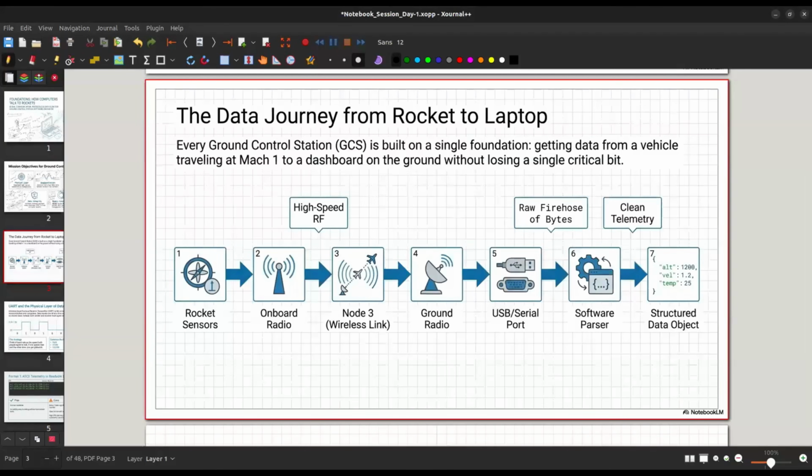Most AI application space seems to focus on analyzing data sent back to Earth. What are the biggest challenges in deploying models directly on board satellites? The biggest challenge is you cannot directly apply the AI algorithm on board unless you have a specific high-end computer for that. The mini computers that I would recommend are probably something you have heard of, Jetson Nano, and maybe Raspberry Pi 5. These are the onboard computers that you have to keep in mind.